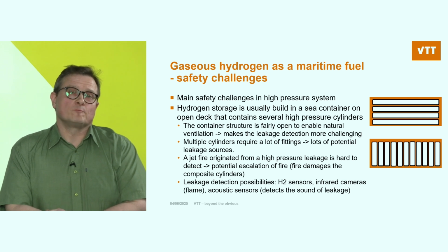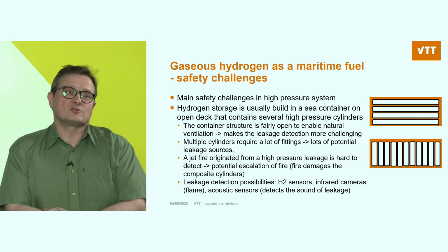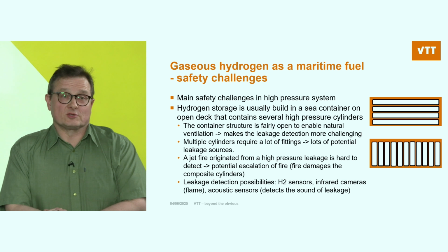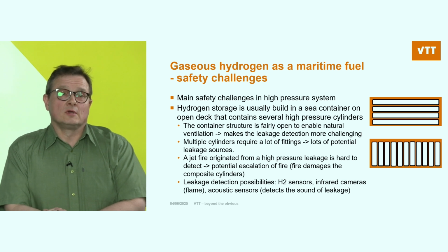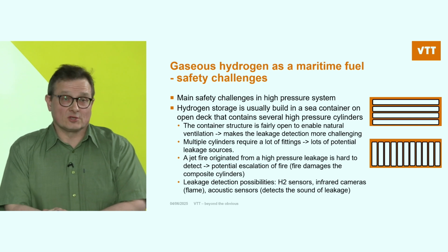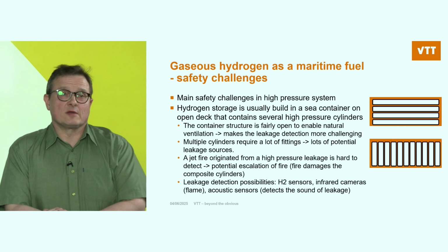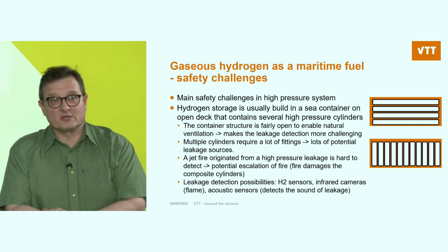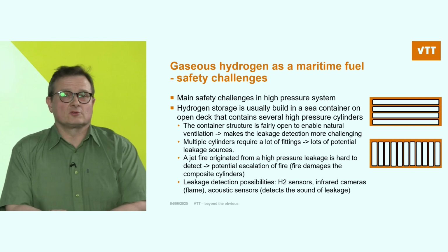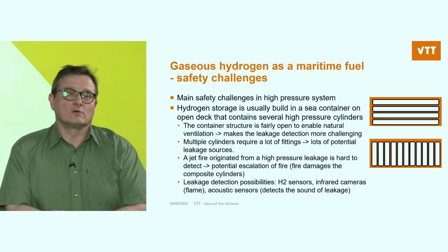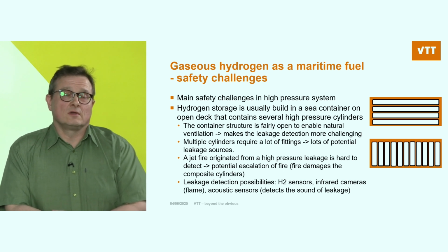And because of the hydrogen properties, it is really hard to detect a small jet fire, especially on open deck. And there is always danger for potential escalation of fire if the fire damages the composite cylinders, which are basically plastic, which cannot tolerate long jet fires.